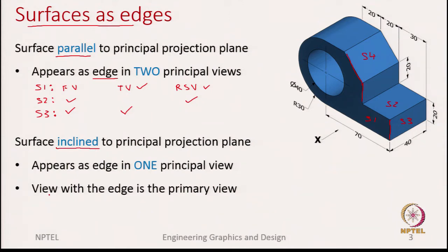You can have a more general inclined plane where it is inclined in to all the three principal planes. Even there you can apply auxiliary views, but at least in this lecture let us not focus on that, because if we focus on the inclined plane and know the concepts, we can extend these even to draw the views for an oblique plane, okay. So, let us again get back to the inclined plane we are discussing, which is surface S4.